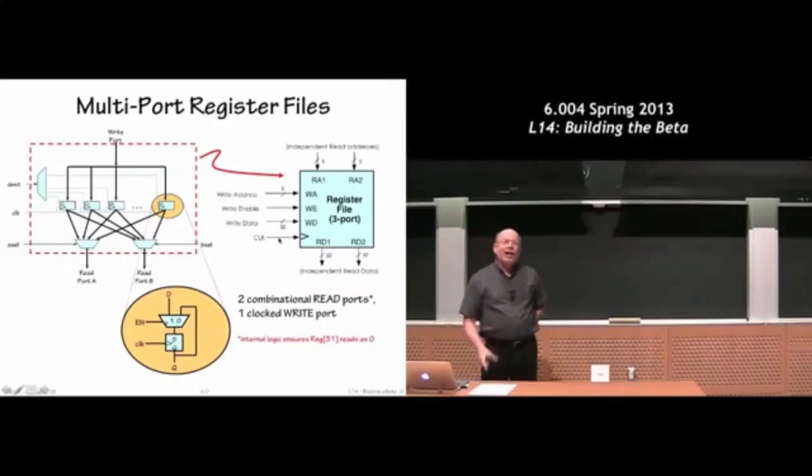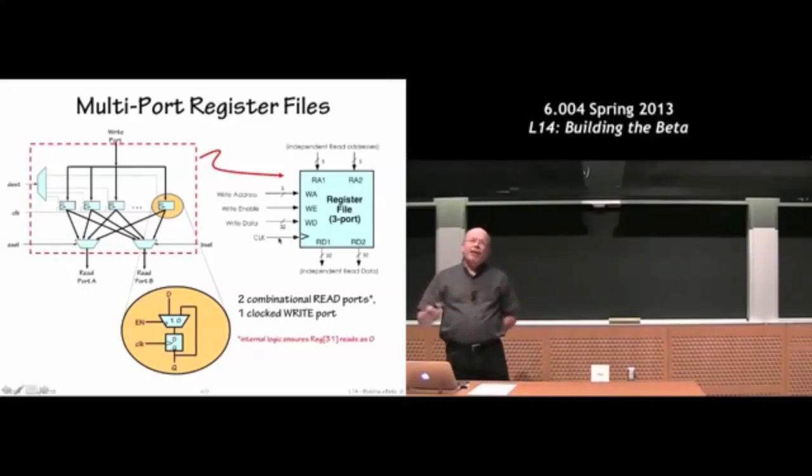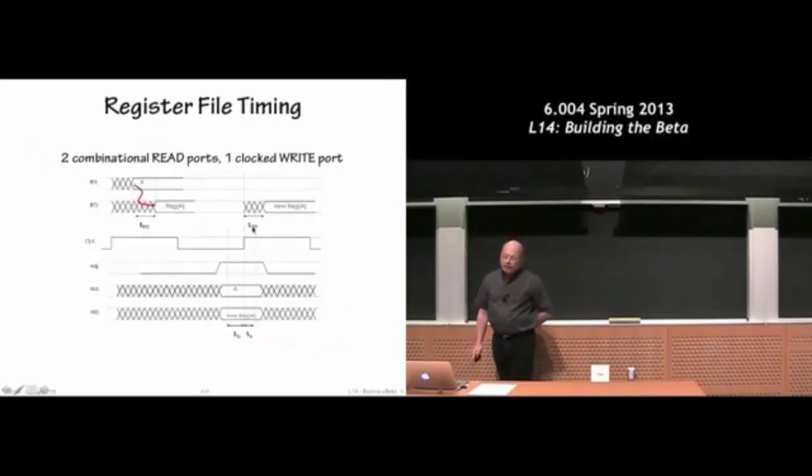So this is really just like a register. The writes happen at the rising edge of the clock. Which register gets changed, if any, is determined by the address wires and the enable wires. And what the new data will be is determined by the write data wires.